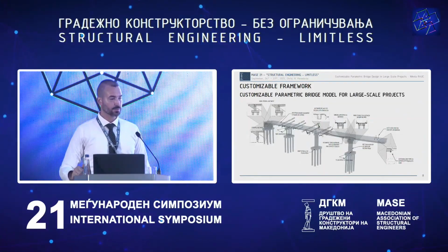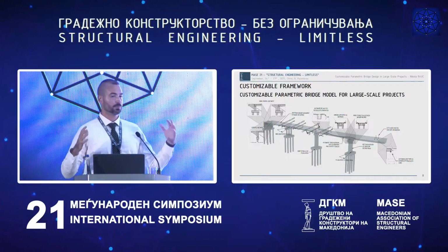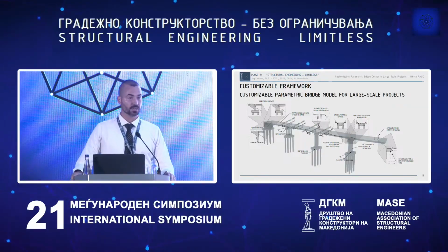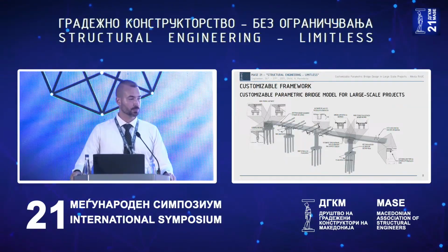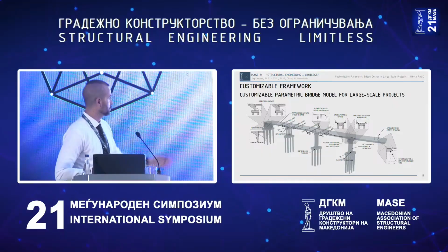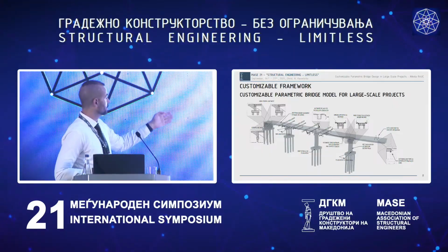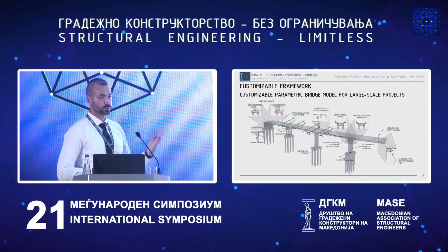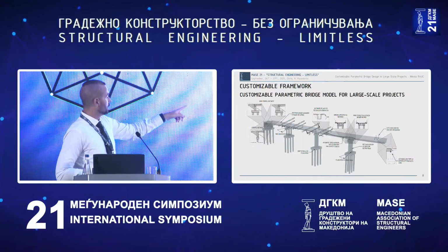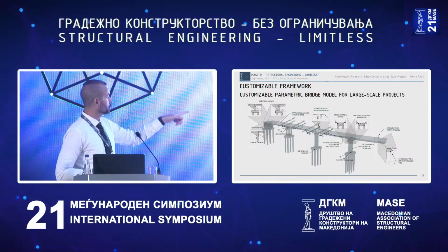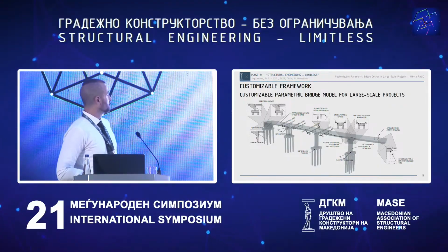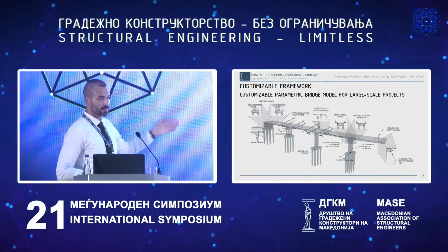But also, this thing is able to scale it up, to make one general parametric model that can cover a vast majority of bridges. And for example, in the company, DB Engineering, we have implemented this. And this is one parametric model that covers a lot of things. For example, if you can see this parametric model, it works with 4 types of superstructure. It covers solid slab superstructure, it covers box section, composite I section girders, and also T-section rib bridges.